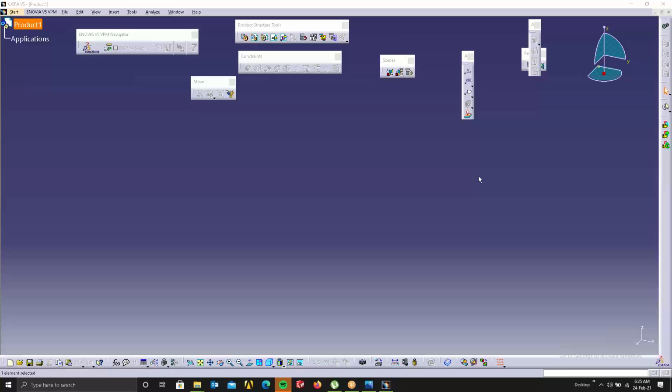You have two things. Take cold plates, for example. You have a housing, the bottom housing, and a top plate. For thermal management, we have a case inside which we put fins: plate fins, plain fins, or V fins, or offset OFC fins. So we have different types of fins. We stack them inside, close them, and vacuum braze it.